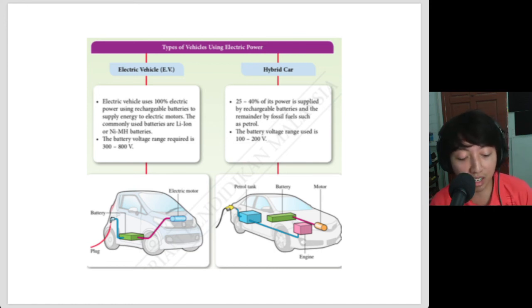And so they have to think, do I need more voltage but increase the internal resistance of the battery, or do I try to put more batteries in parallel so I have less internal resistance but a lower total voltage? These are things that electric car manufacturers have to consider. Of course, the ideal situation is to find a battery that has high voltage but zero internal resistance, which, like I said, we don't have yet.